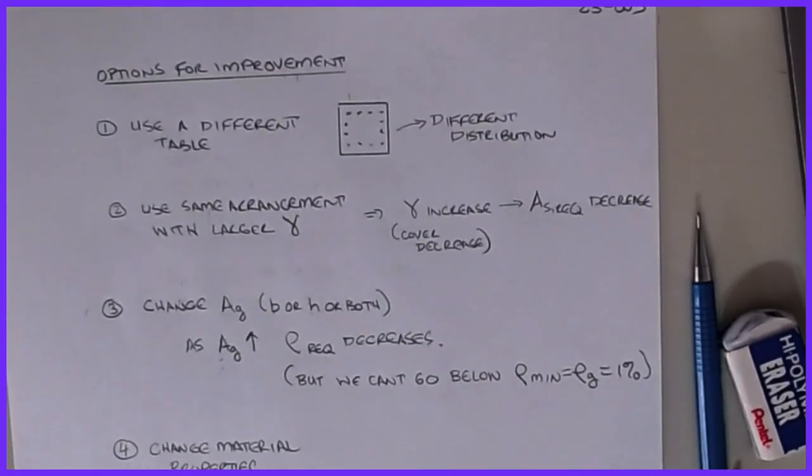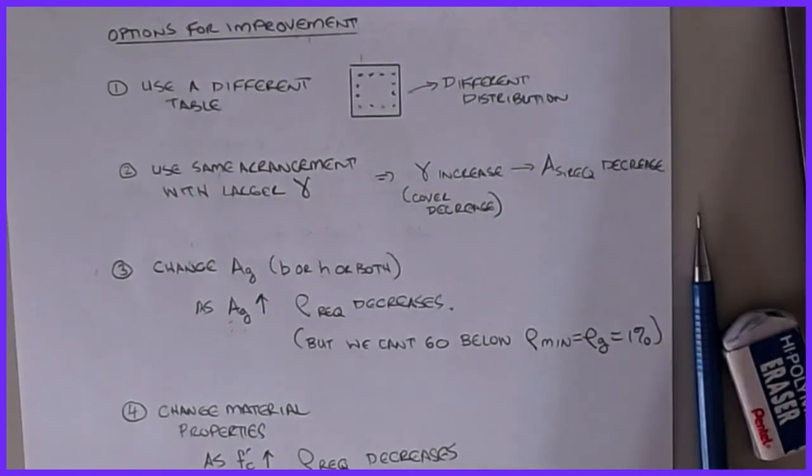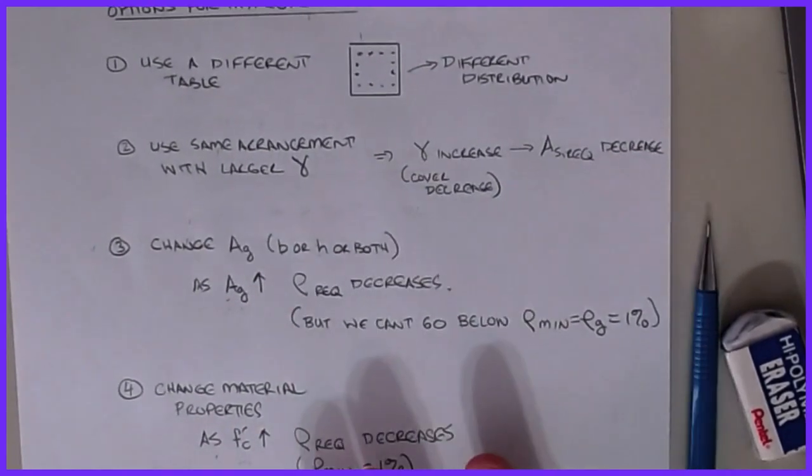Now, as you get better at this, you'll start being able to pick up combinations of axial load and nominal moment acting simultaneously on a column, and you'll start building this library in your mind, if you will, of being able to say, for a certain eccentricity, what size did I need, to get a sense of the values. So I hope that made sense.